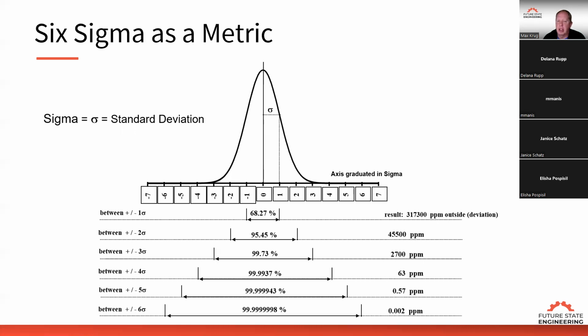If I measure the process, I can take that data and I can chart it on what's called a histogram. On the histogram, I can calculate different statistics. I can calculate the average, right, or the central limit, and I can calculate the range, so the smallest to the largest, and I can calculate the standard deviation. The standard deviation is the amount of variation in the process.